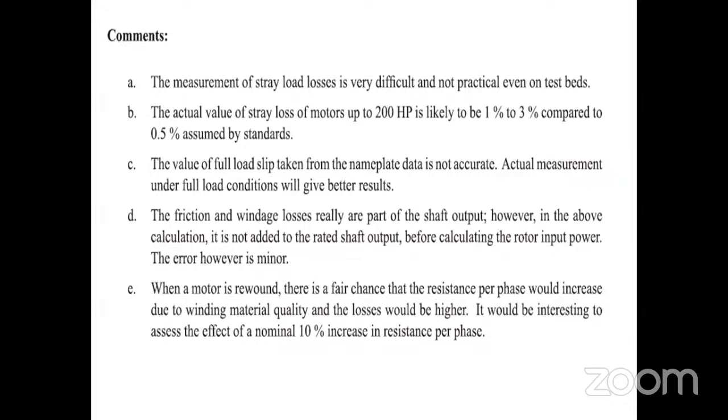When a motor is rewound, there is a fair chance that resistance per phase would increase due to winding material quality and losses would be higher. It would be interesting to assess the effect of nominal 10% increase in resistance per phase. Sir, just remember, 10% increase in resistance per phase.